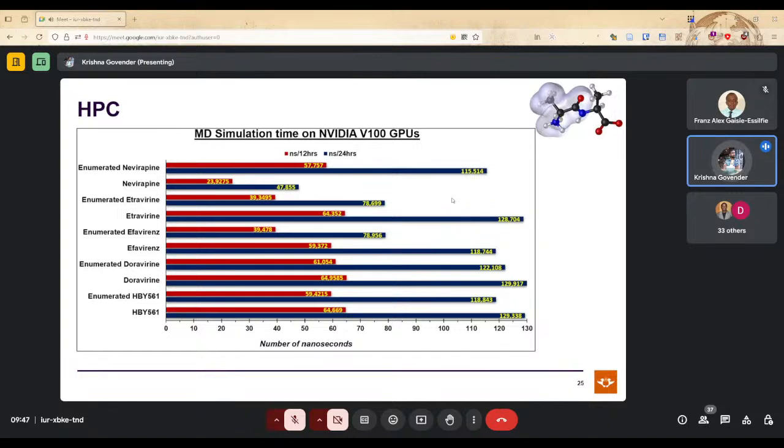So you have to break up your simulation into portions so that you actually have a point where you can restart the simulation from. So in this case, I would go with 50 nanoseconds. I'd run the simulation for 50 and then run the next 50 and the next 50 and so on. And then put all of them together at the end. And the same here. If I had this, I would run this for 20 nanoseconds and break it into blocks. 20, 20, 20, 20 till I get my full 100 and combine them at the end. Because if I had to run 100 here, again, it will run for the 12 hours. I'll get an output, but I just can't restart from that output. So it kind of defeats the purpose, right? So you have to have a point where the job can stop safely so that it can continue with the next portion.